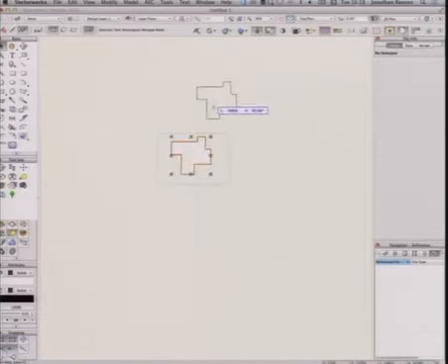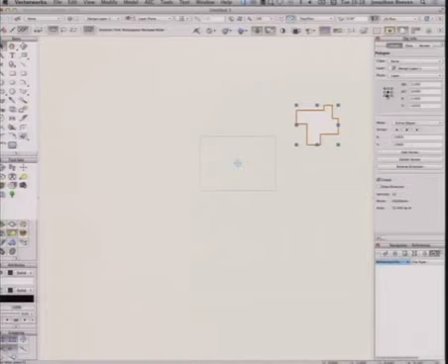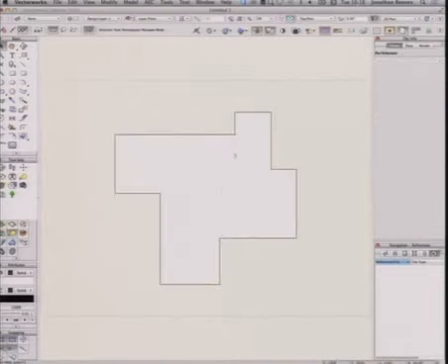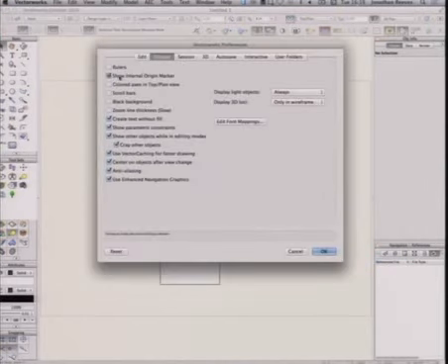Okay, so now I've started. Let's say I have started off my paper. Well, don't ever do this. Don't go and import a survey file. I wouldn't recommend starting a very complex BIM model up in Sheffield or wherever the survey happens to import. Okay, we can talk about origins later, but I would encourage you to essentially take the object, put it onto the center point here, and just put it back onto the user origin or the local origin. And you can see that under there, if I hit the B key, I've got my blue cross. This is my internal origin of the file.